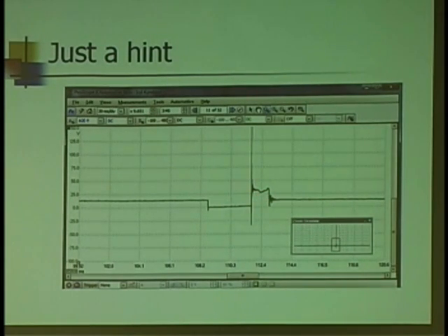Now, remember we talked about the burn line as a representation of the resistance. I would expect the resistance to either decrease, remain the same, or increase, but not go up, down, and sideways all at the same time. What do you think could cause that? Let's see, fuel. Would fuel cause that? If it's either lean or it's rich, right? It's not going to change midstream. So I doubt that. Water? Water in the gas? That's a possibility.